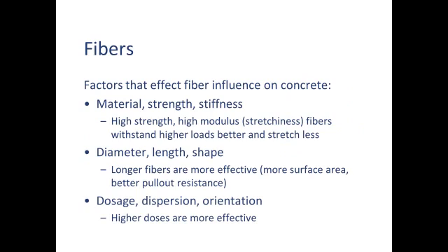The second and third points on this list are important. Short fibers are less effective than long fibers. Thick, long fibers are strong, true, but there's not a whole lot of surface area relative to that fiber than, say, short, very small diameter fibers. It's called the aspect ratio, the length to diameter ratio.